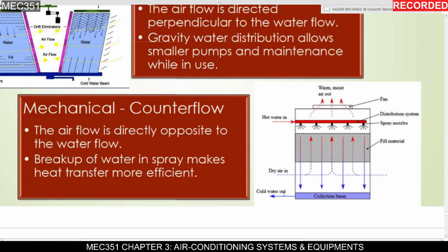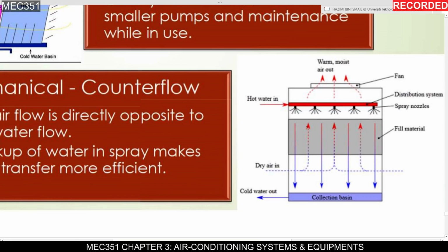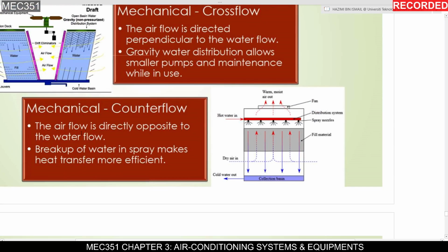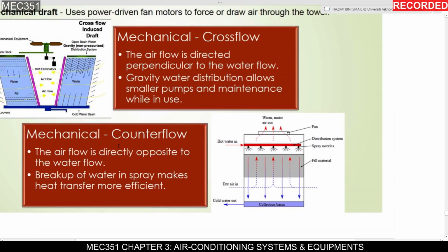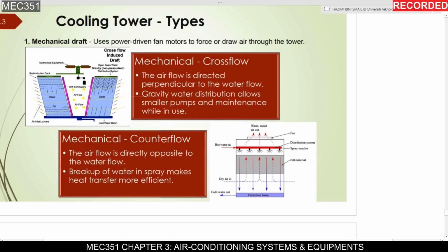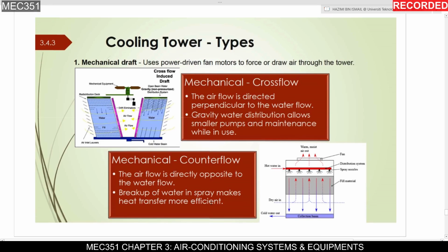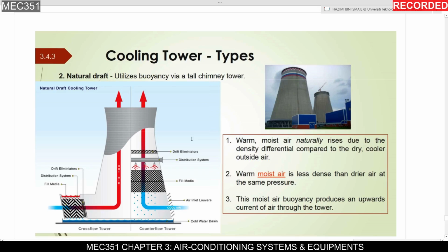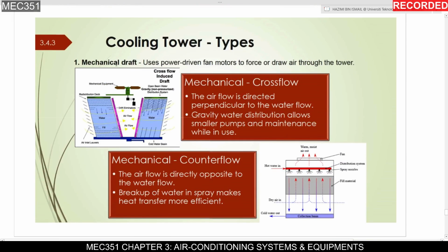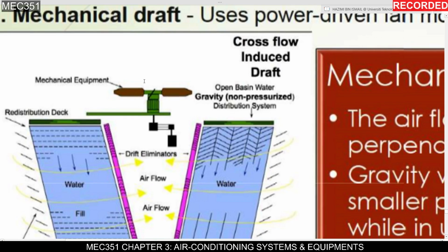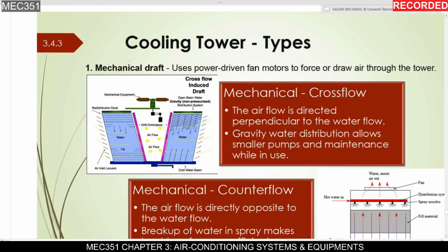In the counter flow, the air goes in the opposite direction of the water flow. You can read by your own, or you can find detailed videos about the cooling tower on YouTube. There are a lot of videos I found on YouTube. This one is the mechanical draft because we use mechanical equipment up there, the impeller that is connected to the motor to drive the airflow.